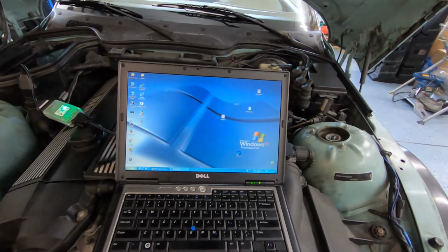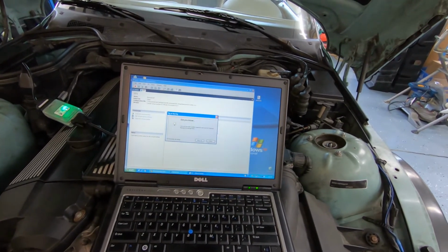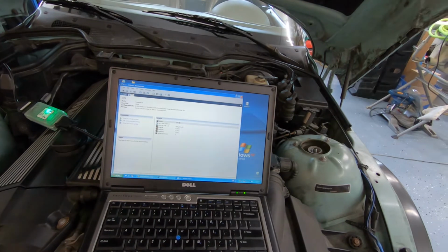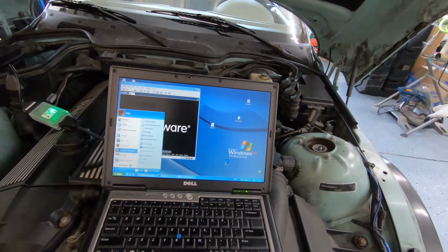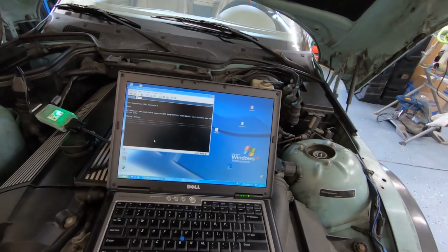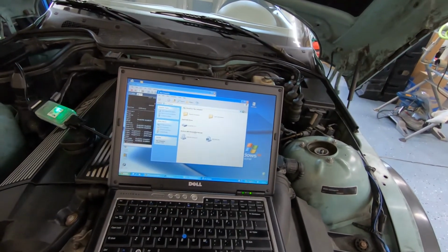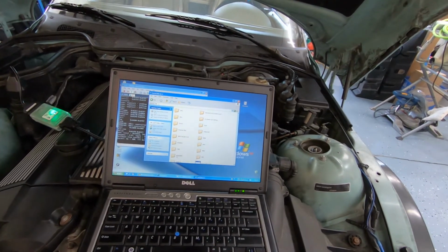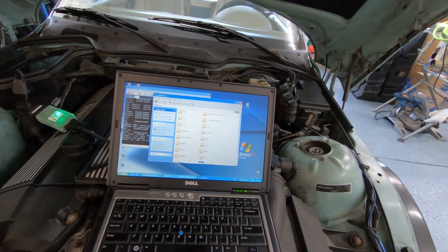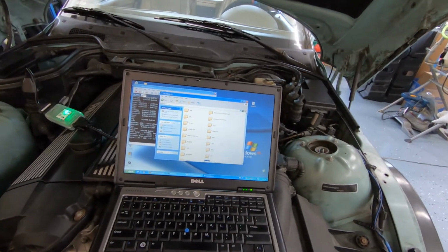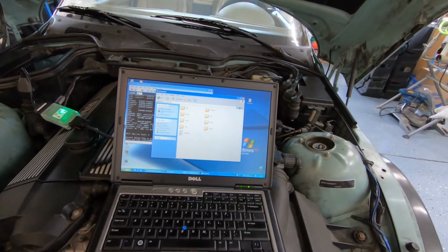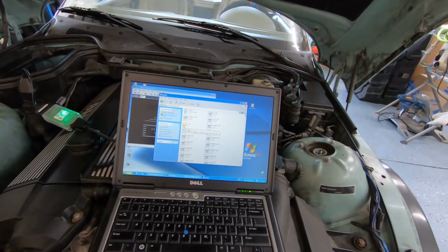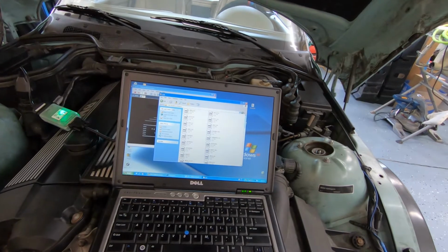How do you get your ZCS for the manual transmission? Good question. There is a configuration file within NCS Expert. I think it's called a DATEN file. Essentially, it is like a reference document for the software for the options. Now there are going to be different DATEN files for all the different series of vehicles. Since we're working on the E36, what we're looking at is